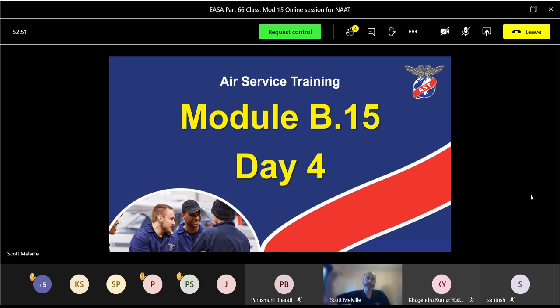But theoretically, if you could keep the speed constant using drag, with a fixed throttle setting, in theory it would just be the P0 capsule. But as you're speeding up coming down, the P1 capsule, the bottom capsule, will also try to increase or expand, which will again try to open. So between the two of them, they will get to a certain point where they have the right gap, which is restraining the servo pressure line to increase fuel appropriate to the air required. Okay.